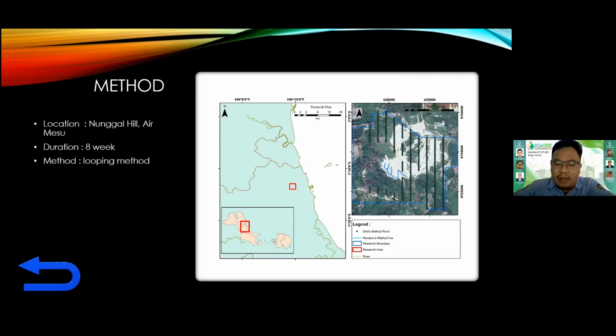Data obtained from the acquisition will then be corrected as much as possible to remove every disturbance that happens in the research area, such as the International Geomagnetic Reference Field value, or IGRF, and the inclination value in the research area. Every value mentioned earlier can be obtained from various official websites such as geomag.bgs.ac.uk.